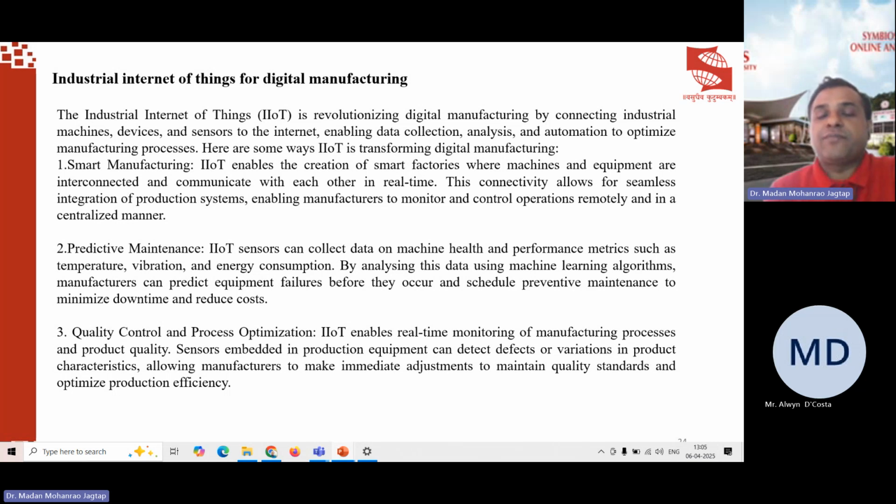When we have vibration measurement equipment, with the help of frequency analysis, I can tell whether the fatigue level of that machine is achieved, whether that machine requires maintenance, whether that machine requires repair. That can be identified with the help of IIoT sensors. What amount of energy this machine is consuming can also be identified with these IIoT sensors. The various parameters we can track with the help of IIoT sensors.